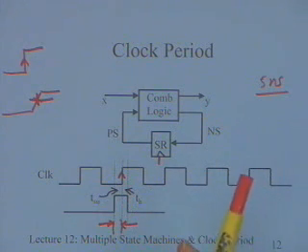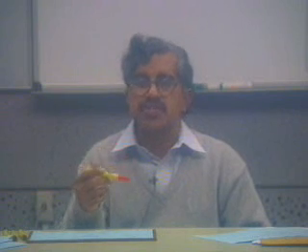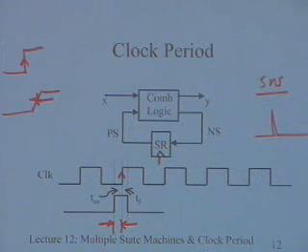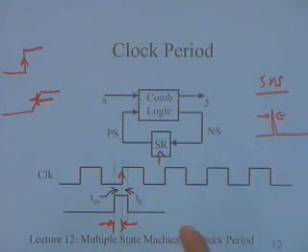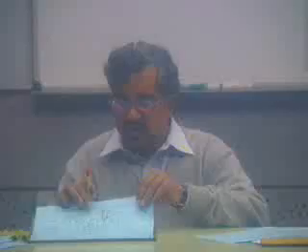When you talk of synchronous designs, when you talk of non-synchronous control inputs, then there will be a specification of minimum width. A clear, to be effective as a clear, to clear the counter, will require that it should have some width. It cannot be a spike of, let us say, 0.1 nanosecond; that will not be able to clear the counters. There will be a specification of the minimum width. This is for asynchronous inputs. For synchronous inputs, we will have the specification of setup and hold.